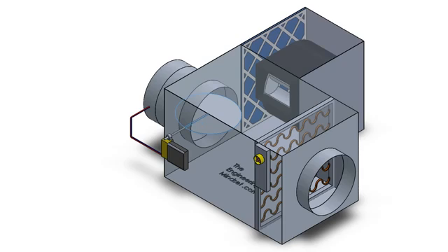You get the air turnover in the room. And it also reduces the chances of cold air being dumped out of the diffuser onto anyone sitting below, as that would be very uncomfortable for them, and the staff will become sick, and you'll get sick building syndrome and lots of calls for maintenance, etc. So you want to avoid all of that. So sometimes, yeah, fans are put into these little boxes to help the performance.